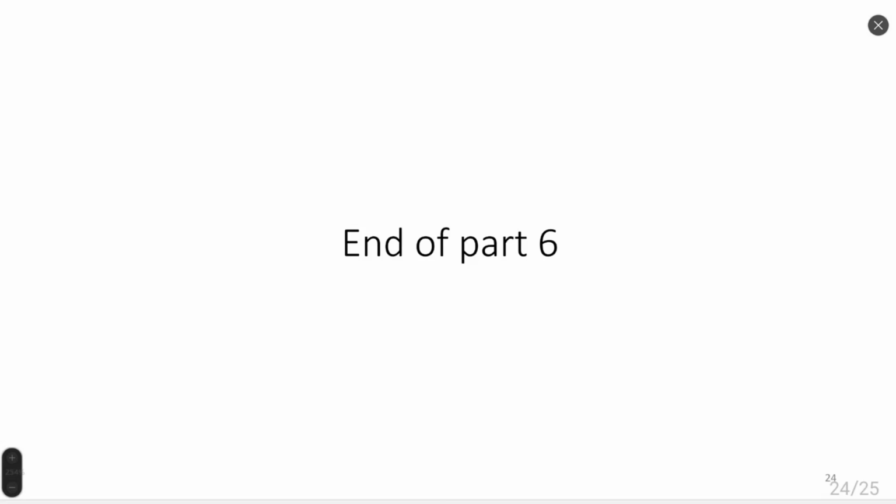Oh, nice question. Thank you. This problem is typical when Inviscid flow does not converge, especially when you choose a high order of approximation. Probably you chose second order of approximation for Inviscid flow. Is it true? Yeah, that's correct. So now we understand. The problem is called computational instability, that I tried to explain probably last time.